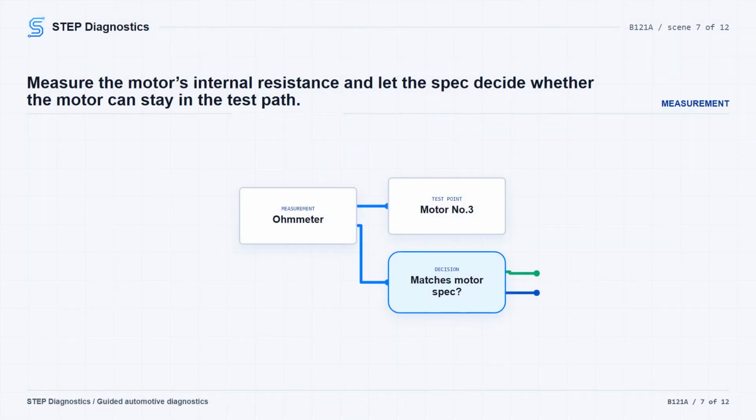With the climate control unit 32P connector disconnected and the mode control motor 7P connector disconnected, measure resistance inside the mode control motor between No. 1 and No. 3 on the S5V and SenseCOM circuit. The expected value is 6K ohm plus or minus 1.8K ohm. If the resistance is not 6K ohm plus or minus 1.8K ohm, replace the mode control motor. If it is within that value, continue to the next motor movement and feedback check.